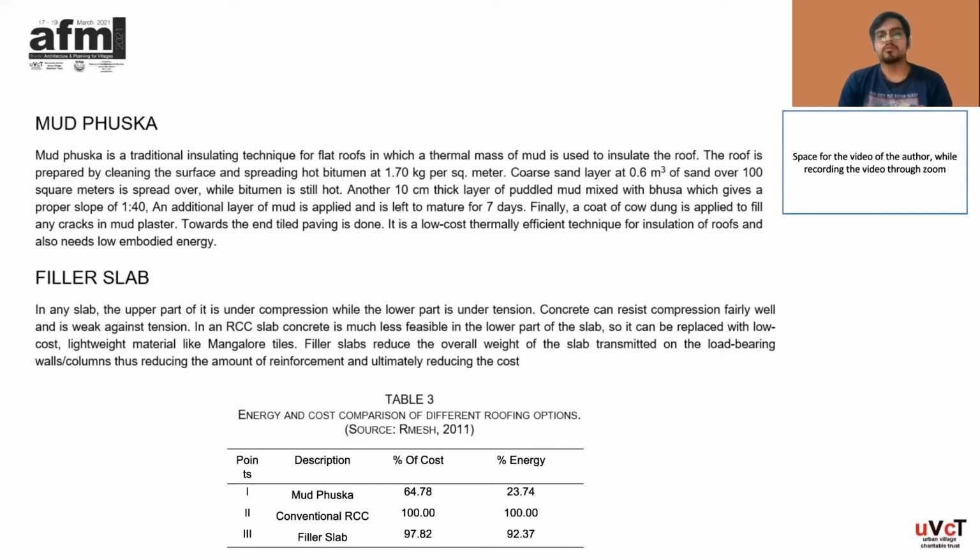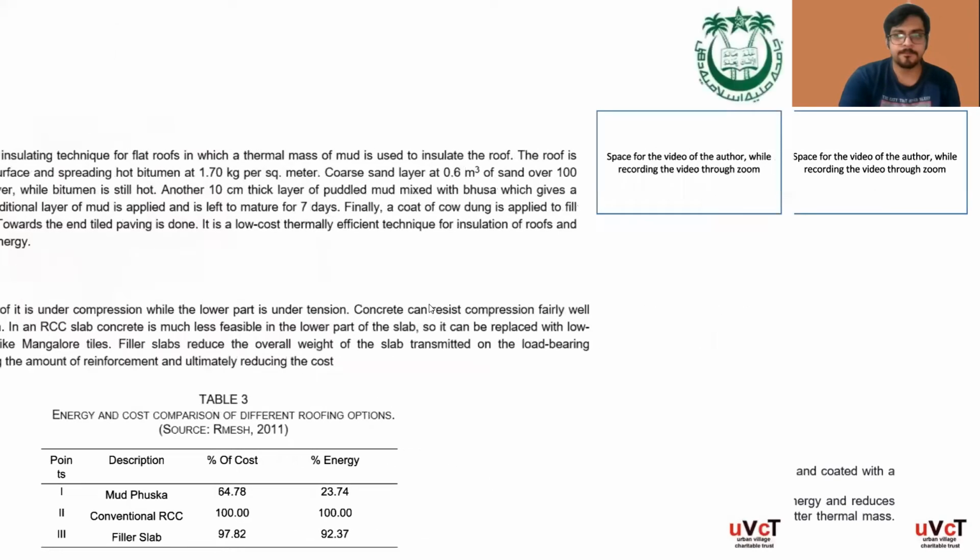Filler slabs reduce the overall weight of the slab transmitted to the load-bearing walls and columns, thus reducing the amount of reinforcement and ultimately reducing the cost of the overall structure. Table 3 gives you the energy and cost comparison of different roofing options. Let's move to the next slide.